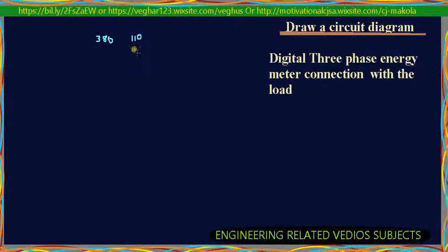So this one we're going to look at is 110 volts and the current is 5 amps, so it's stepping down from 20 amps. The CT, this is the CT, steps down from 20 amps to 5 amps, so that the meter cannot be damaged by the current flowing through the line. So we'll start by drawing the circuit breaker and continue on.